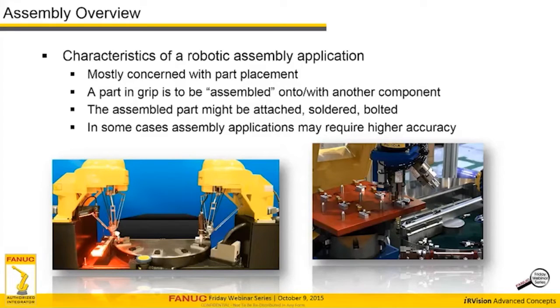However, when we're talking about flexible automation and making a robotic precision assembly cell, machine vision plays an important role in turning that cell from just what it would be, an extension of hard fixturing, into a truly flexible cell where we can have the parts coming in a variety of locations or in possibly unknown locations or imprecise locations being picked and placed precisely into the assembly to complete or at least advance the assembly of that particular component.